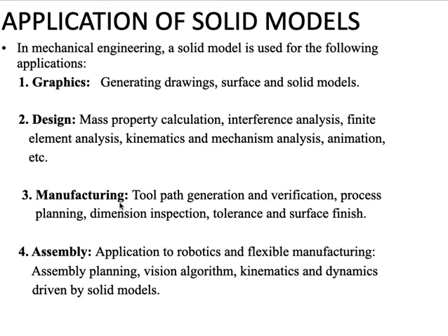The third application is in manufacturing: tool path generation and verification, process planning, dimensional inspection, tolerance and surface finish, and all. It comes even up to assembly as well. Then there is the application to robotics and flexible manufacturing, assembly planning, vision algorithms, kinematics and dynamics driven by solid models. These are some applications of solid models.